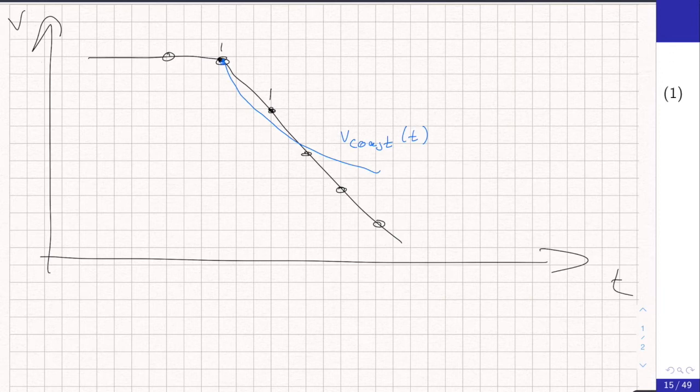That started here with v0, and then to determine whether or not the profile needs propulsion or if we need braking while we follow the profile, we can compare the end velocities at this point here. If the end velocity is higher than the coast, that means that we need propulsion. If the profile would have been like this, that means that we need to use braking. So this illustrates how we can use the coasting solution.